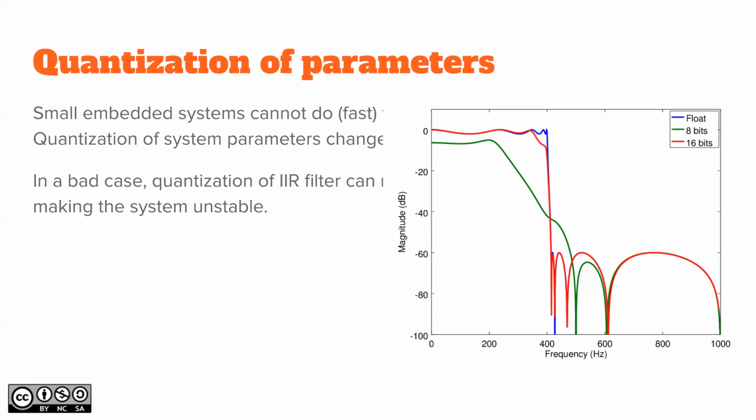And okay, you can actually measure the performance also, how fast it goes. One way to go is basically just test how fast your system is doing MACs, then do simple arithmetics and see if you can use floating points or not. My preference is always to use floating points if the system can do it.